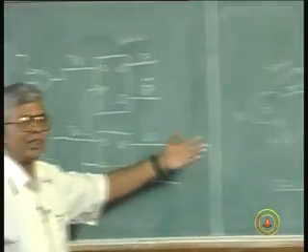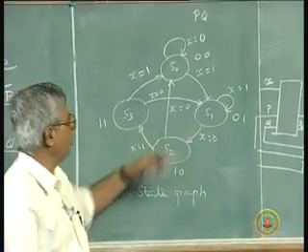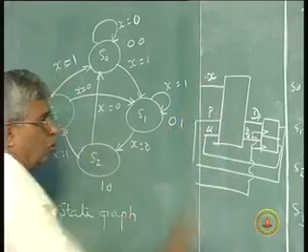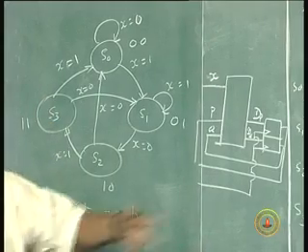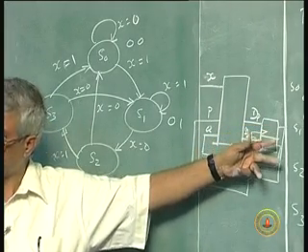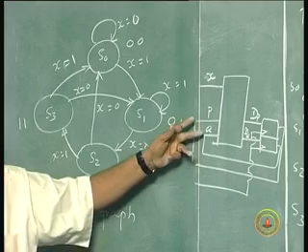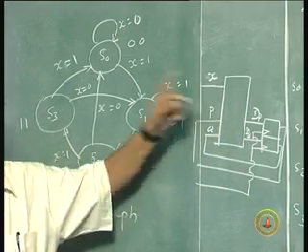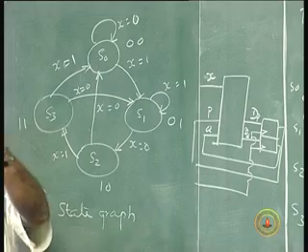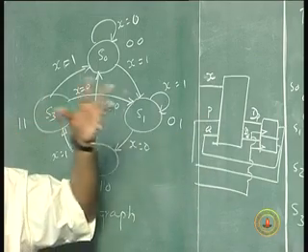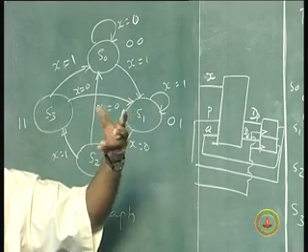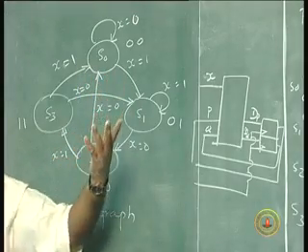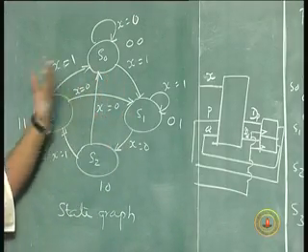Of course, I didn't have anything in mind. I just assumed a circuit with one input and 4 states. 4 states require 2 flip flops. Use 2 flip flops. Those flip flop outputs have to be fed back as input information. So 2 state variables P and Q, 1 external input X. So P, Q, X are the 3 inputs to the steering logic. So this could be anything. It could be a traffic light controller, for example. There may be 4 states in which X may be an external input.